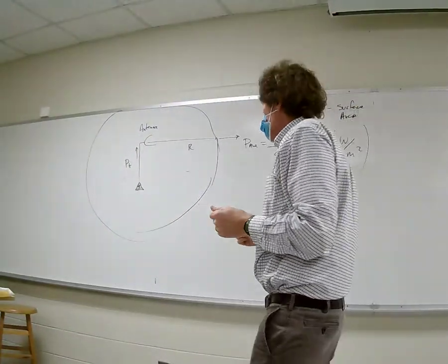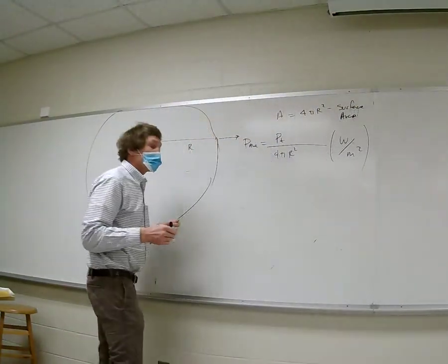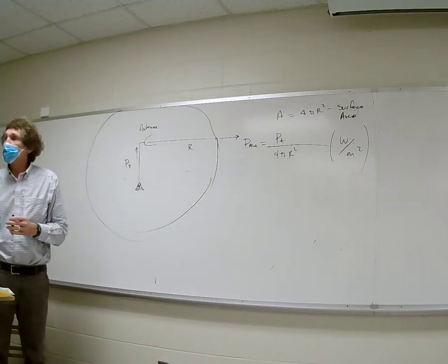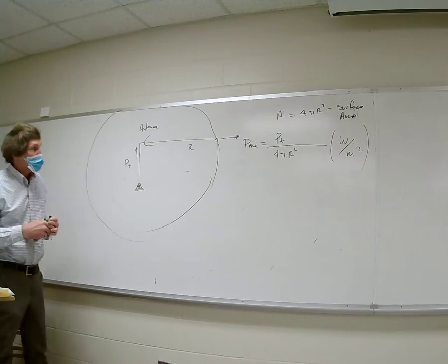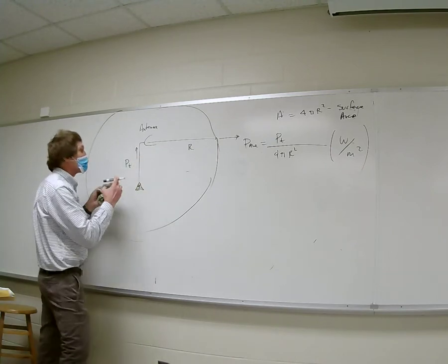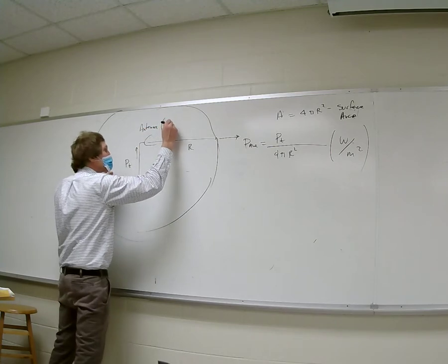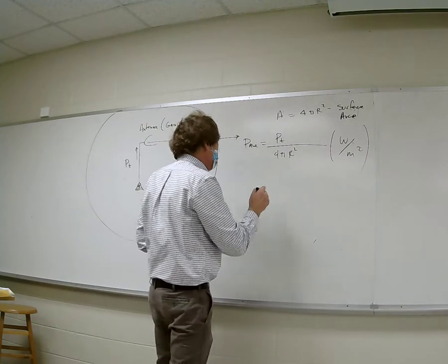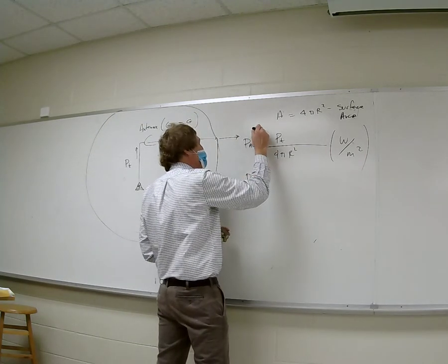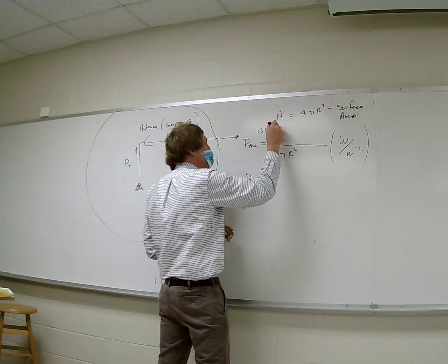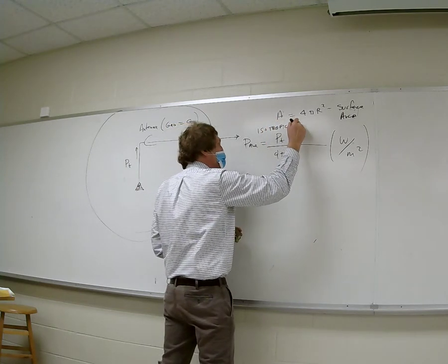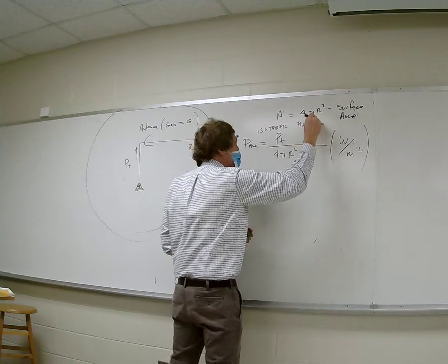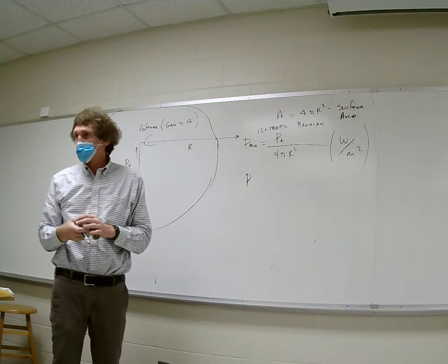But it's not true with antennas. So if we have an antenna, we have something that focuses the electromagnetic power, and it's called the gain. Think of it this way. The actual power density of this antenna has a gain, G, and that will be a function of angle. Now, the average power density, this is isotropic, by the way. Isotropic power or radiation simply means that it's distributed equally in all directions.